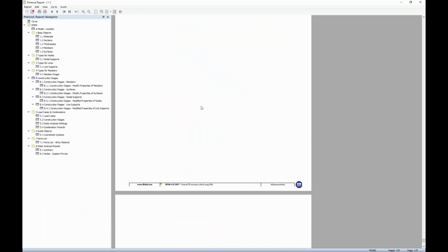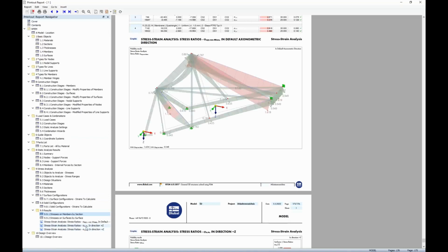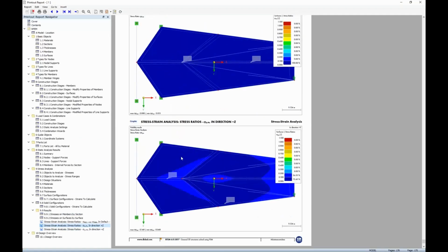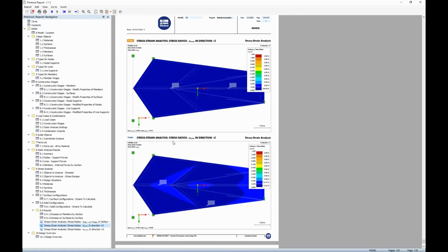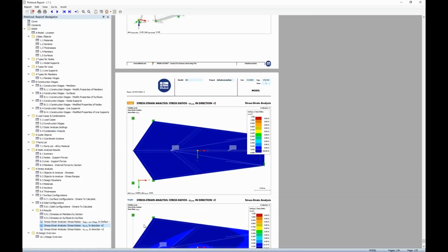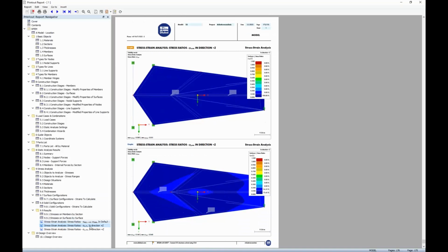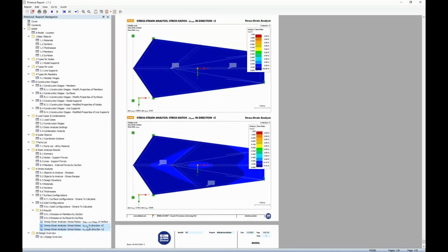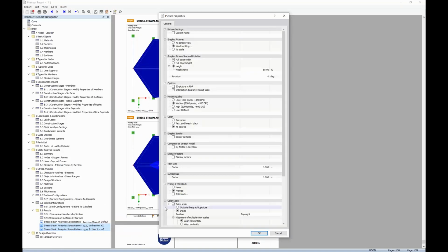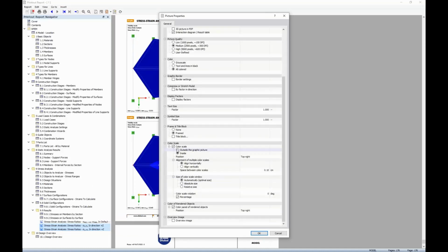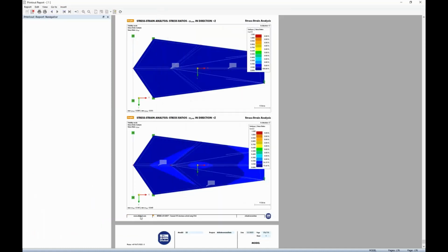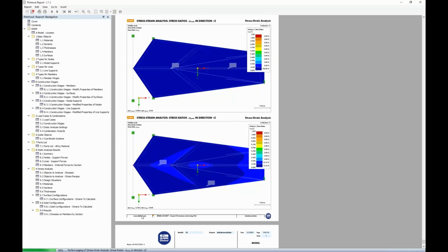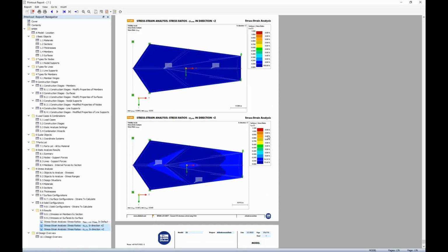document, and when it's updated it's regenerated and you have all these pictures inside. So this is not a big deal, and to bring in some result pictures. What is not nice here is if the color scale is inside the picture, so you can go to properties and say please print color scale outside graphics, and the program is updating the pictures where the scale is outside.